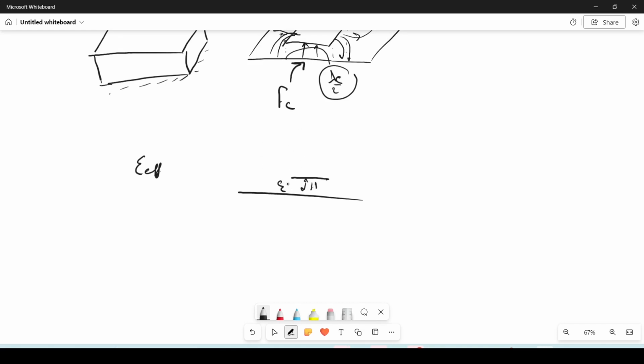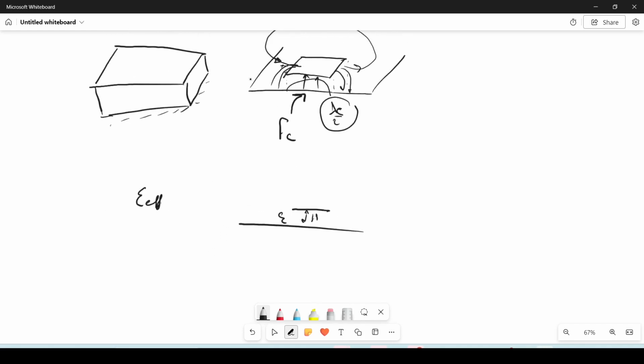Generally, if everything is closed, like a cavity like this, and here is epsilon, it means that the solution sees epsilon anywhere there, whatever metals I draw. But here it's a little bit different. I see something definitely less than epsilon, because if the cavity were entirely filled with this epsilon, I would already get epsilon. So we are expecting some value between 1 and epsilon r, the relative one.